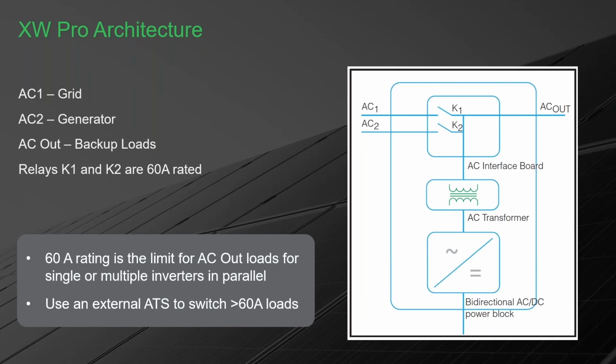When you parallel these relays, and that happens when you do multi-unit design, you have 1, you have 2, you have 3, you can't guarantee that the current is evenly going to split between the multiple relays.